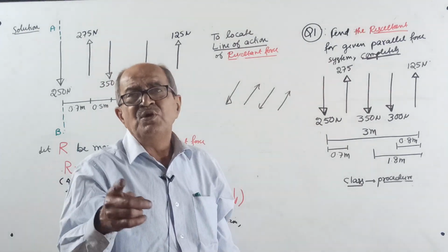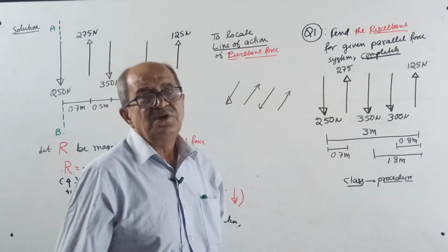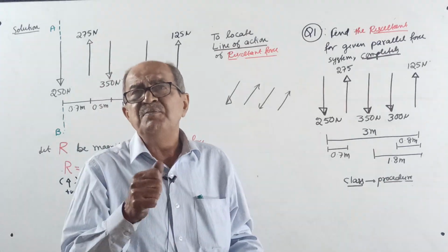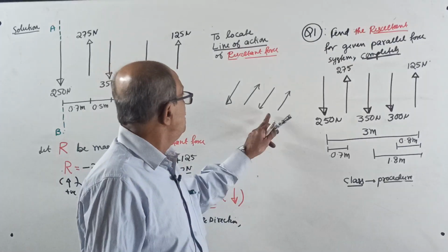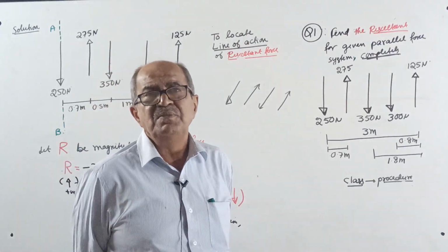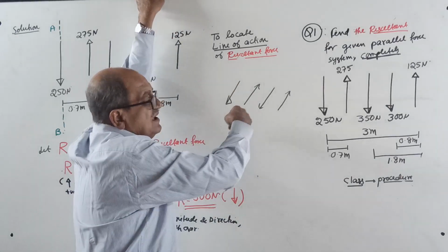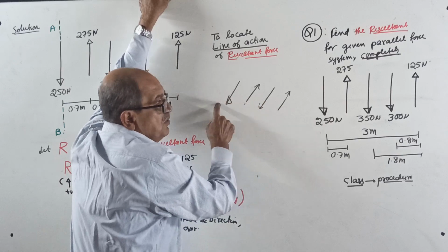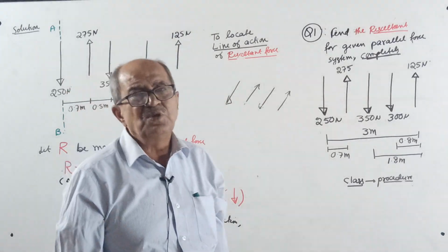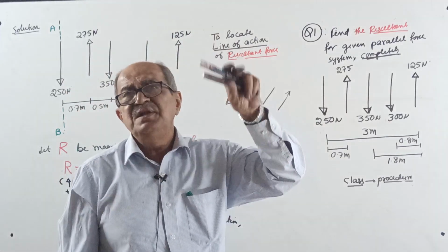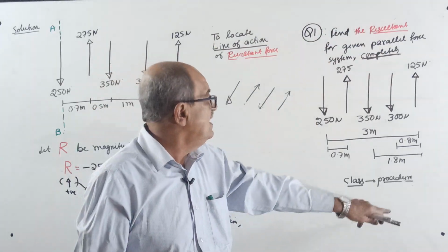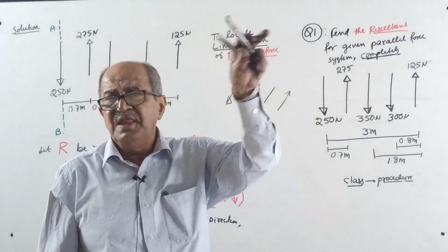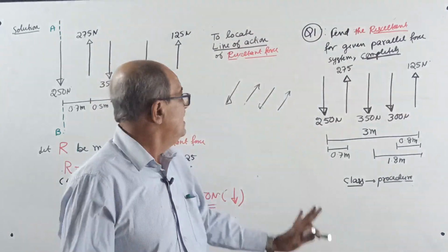If it is a coplanar force system and an inclined force comes, you require resolution. You should write it in the procedure; in the notes I will write it in big letters. In a parallel force system, even if all the forces are inclined, as long as they are parallel to each other, resolution is not required. Why? I will tell you when I solve the question. You write that in the procedure sheet.